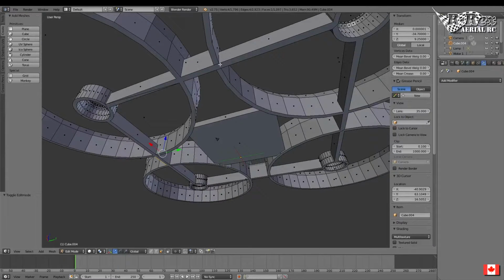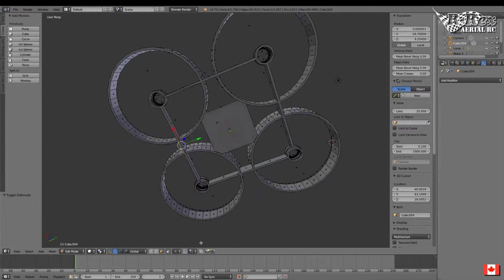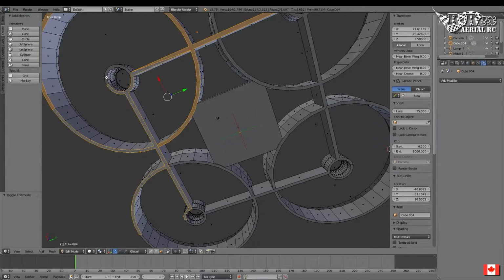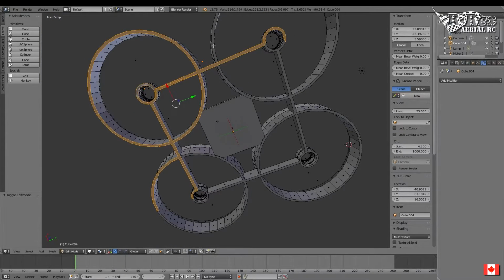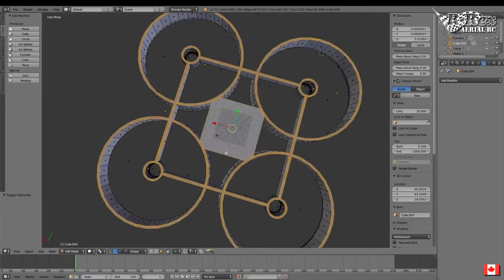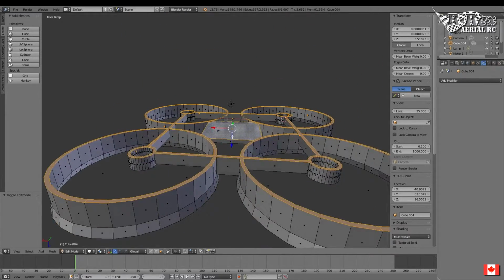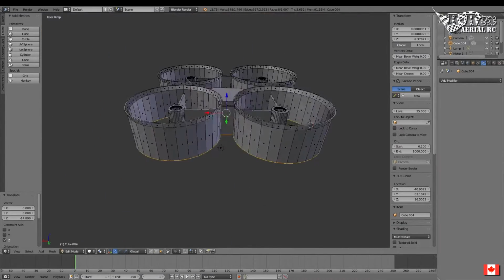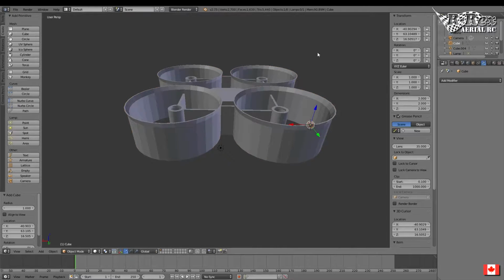Tab. I'm going to do what I did last time, actually. So let's go select the faces. Remember, these were cut to 5.5, so that's what we're going to do again anyway. Done. So I've now selected all of the lower faces. I'm going to drag them up. Create a cube. 0, 0, negative 50. There we go.